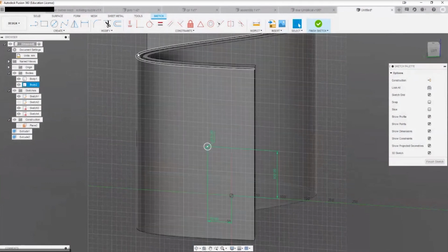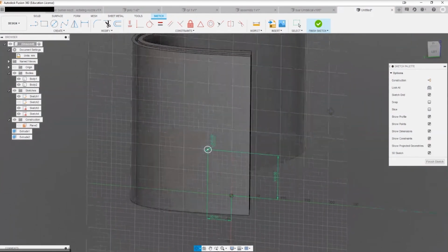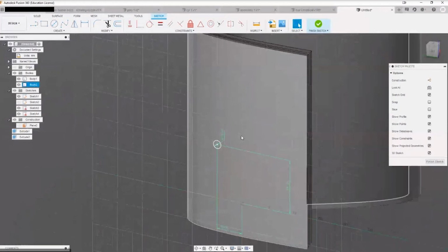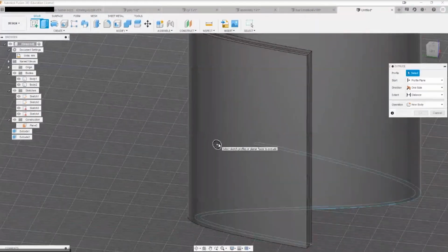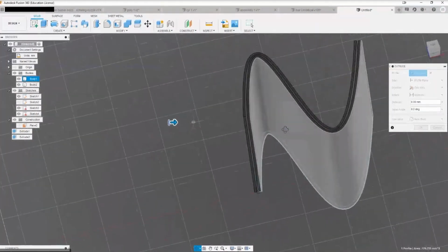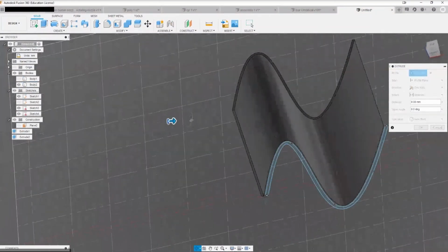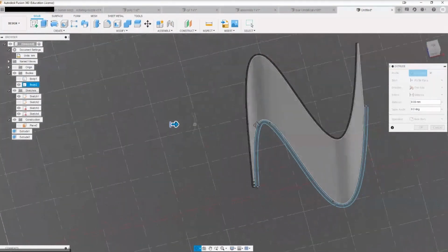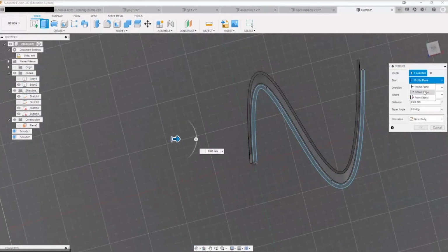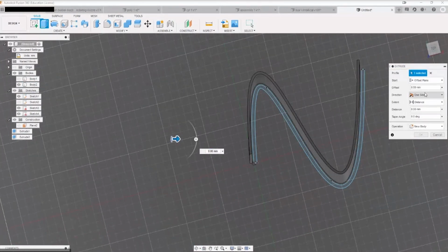So another question was, how do you assemble them? But right now I'm going to show you how to design them and then create separate components, and then I'll show you how to do an assembly of that after. Okay, so if we want to create that pin, let's switch off the second body. So the pin's got to be coming out of this surface, right? Let's go with an offset plane.